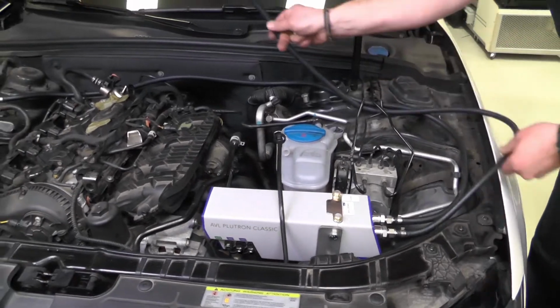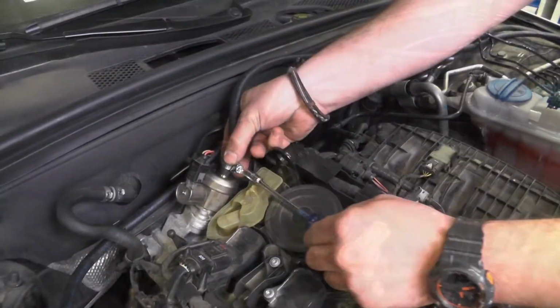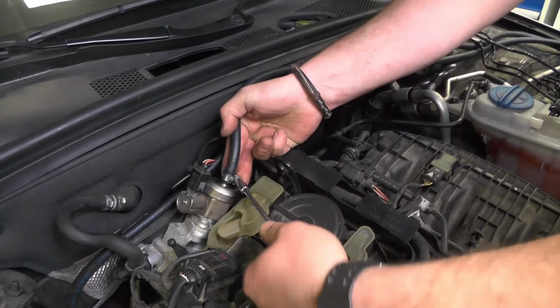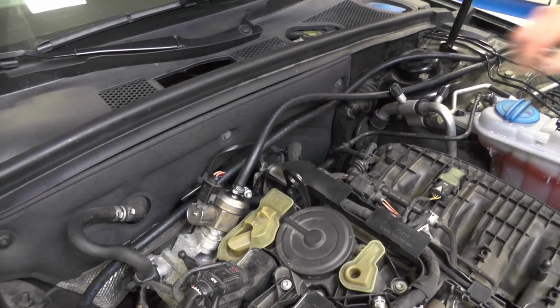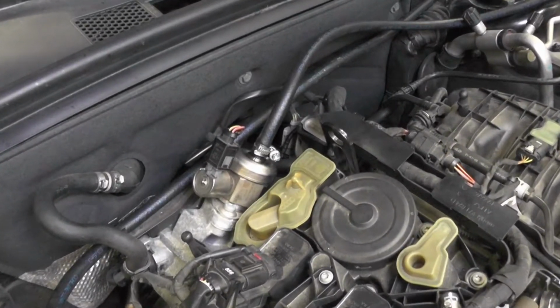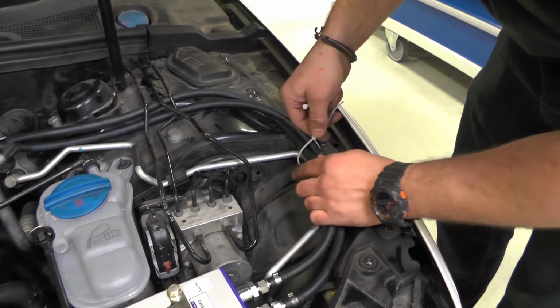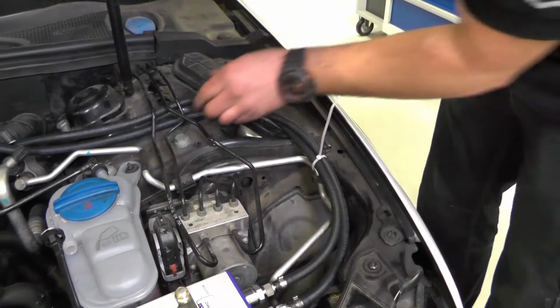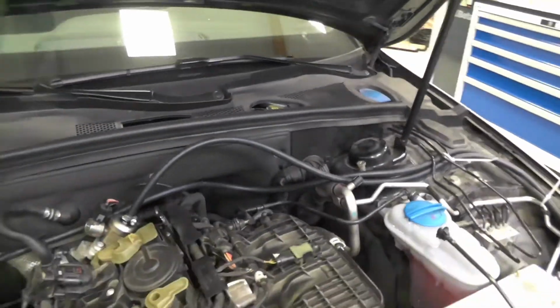Now connect the end of the second hose to the high pressure pump inlet connector. Now we are certain the right fuel is inside the flow meter, and at the same time we have purged the air from the hoses. As a last step, the fuel lines need to be fixed for safety. We are using zip ties to secure the fuel lines inside the engine compartment.